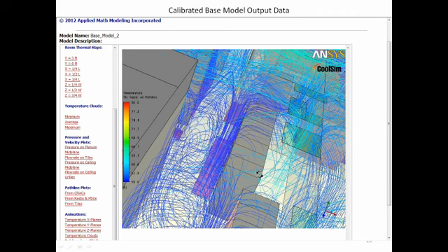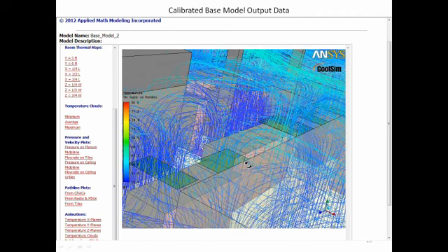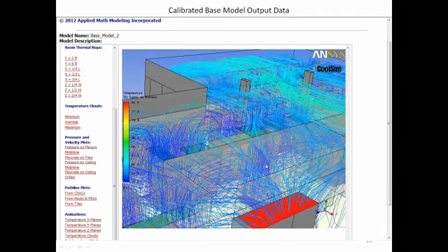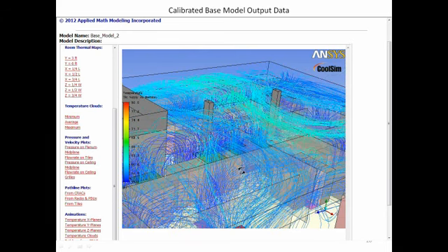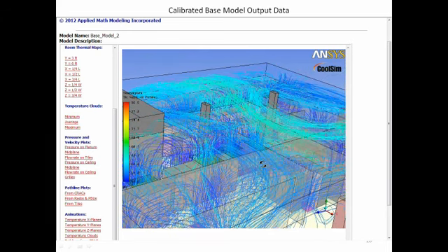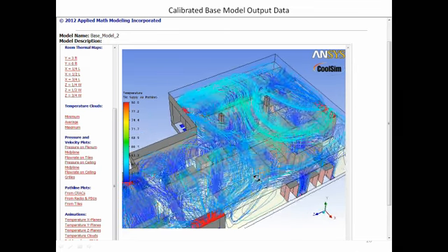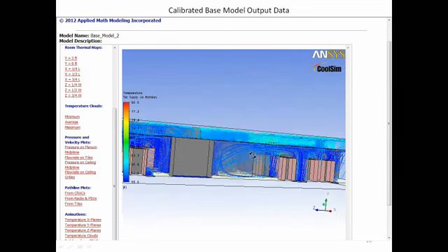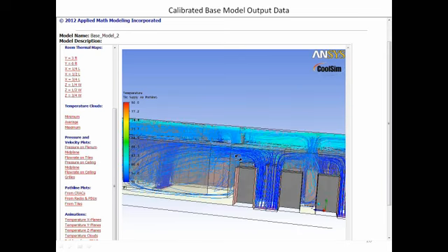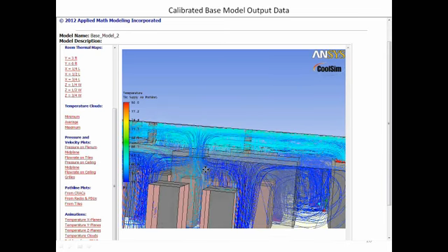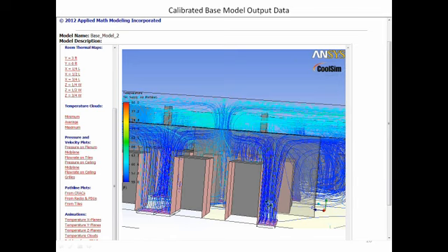You should see no flow in the return ducts because all we're showing here, Liz, is just supply, right? Exactly. It's very cold air and it's just blowing all over the place, way over and above the racks. Right, just because there's way too much coming out of the perf tiles. Yeah, look at it blowing by right here, and this is a good example of bypass airflow coming up, not going in the rack at all, going right back to the crack unit. And going back cold, as you pointed out.